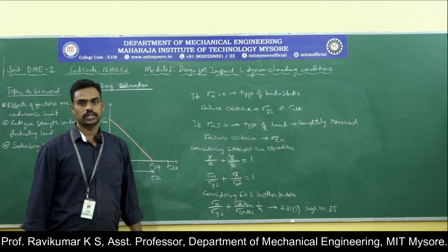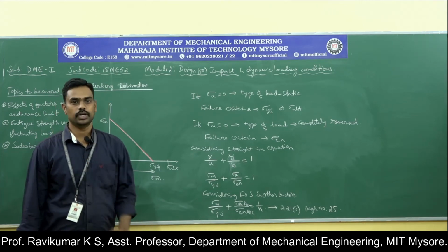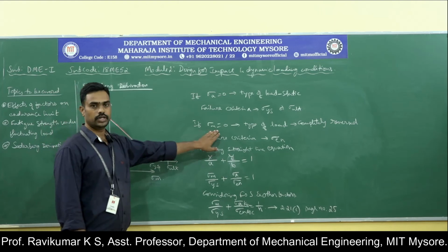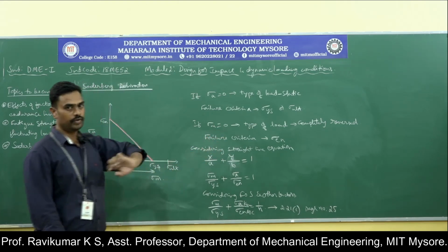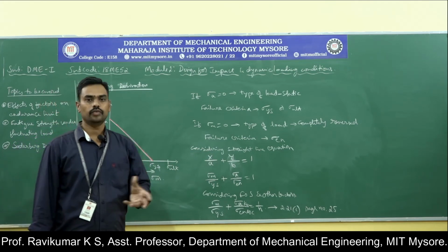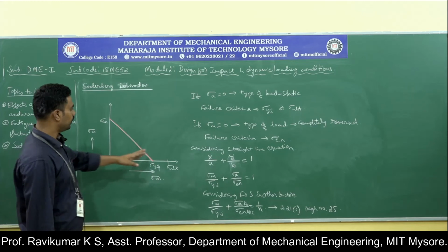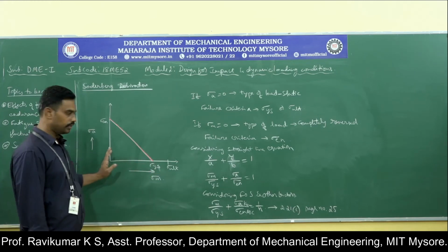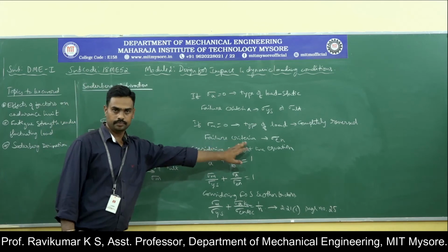In the reversed cycle or fluctuating one, you will find mean stress is equal to some number, but in completely reversed, that is the worst condition of the fluctuating load, you will find mean stress is equal to 0, where the load will be changing in its magnitude, positive to negative. Okay? If the mean stress is 0, then the criteria of failure will be endurance limit.